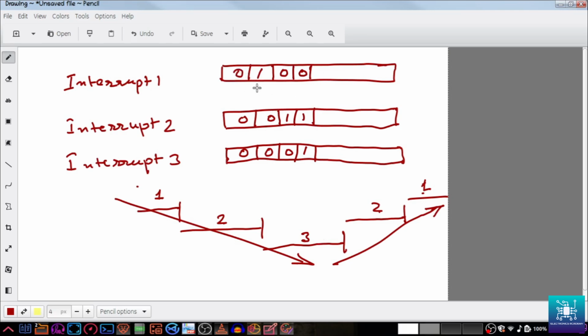Now let us see if we split it up as 3:1, keeping the bits the same, how it looks. We separate out the higher part: we make the top 3 bits a group and 1 bit a sub priority field.